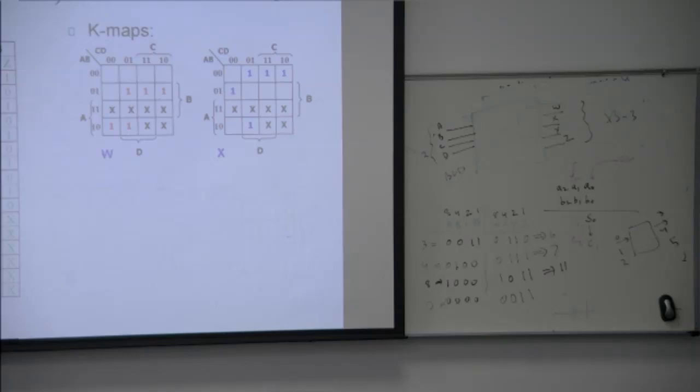For this case, the valid inputs will be the inputs, and this becomes the output. So now you swap it. These are the inputs and these are the outputs. So this will become the left hand side, and this will become the right hand side, and then you derive. So now in BCD, okay. Now if you want to convert from XS3 to BCD, how many ones for A? 2. How many ones for B? 1, 2, 3, 4.